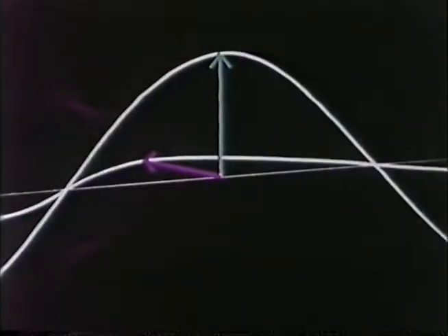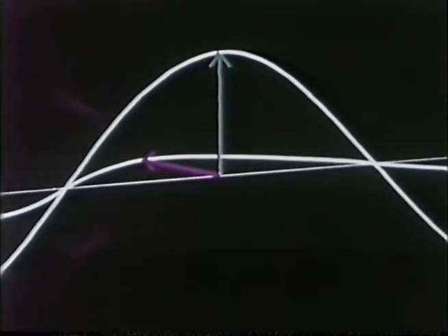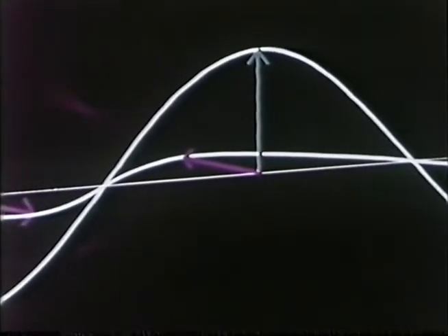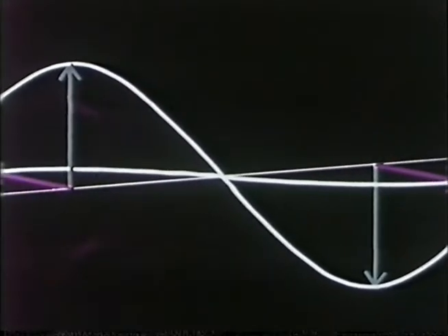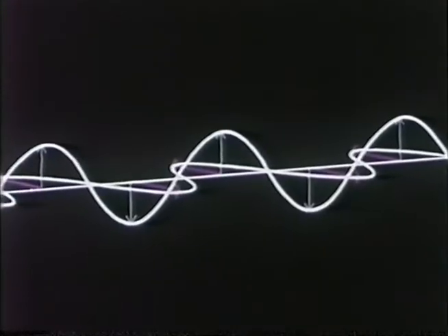Vectorially, these lines represent the peaks of the radiating waves. Notice that their direction reverses at the next half cycle. Since the peaks of these two waves occur simultaneously, they are in time phase. The traveling waves are therefore said to be in time phase and space quadrature.